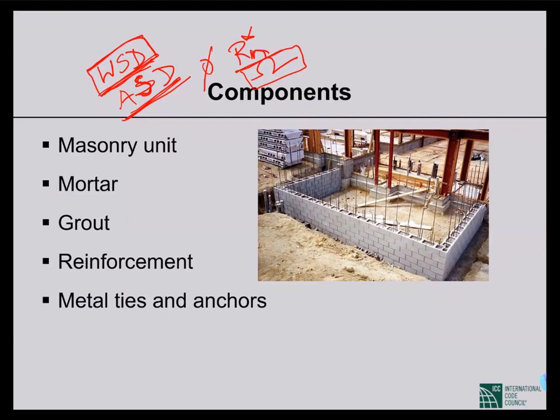I have to check, but all those specifications are mentioned in part 5, chapter 2. So here in part 6, chapter 7, only 4 types of masonry units are mentioned: burnt clay solid bricks, burnt clay hollow bricks, burnt clay facing bricks, and concrete hollow blocks.